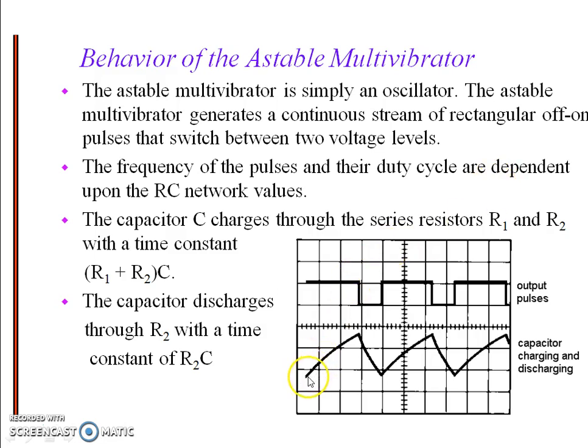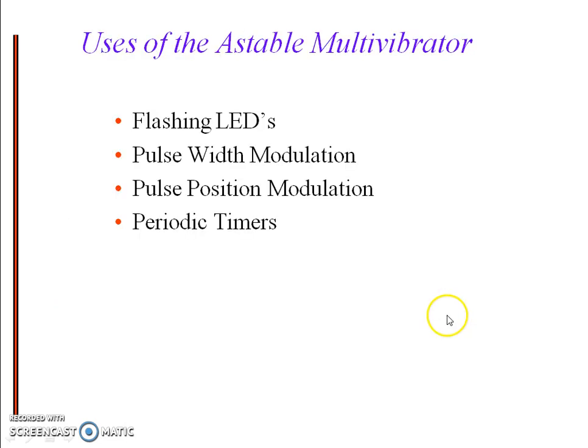The value present here will be 1/3 VCC and the value present here will be 2/3 VCC. This curve shows the charging and discharging of the capacitor, and this shows the output pulses.